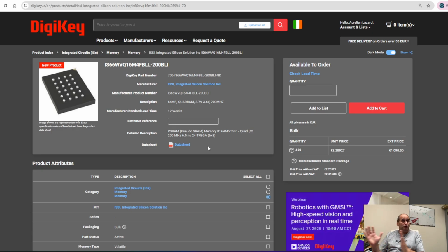Now, if that's not your use case and you have a computer which is just fetching instructions or data, reading and writing in the memory in certain places and everywhere, at certain times, totally random, you need refresh. You need to let the part refresh. So they kind of hide those refresh cycles behind the scenes. The part does this behind the scenes, but that comes with a penalty.